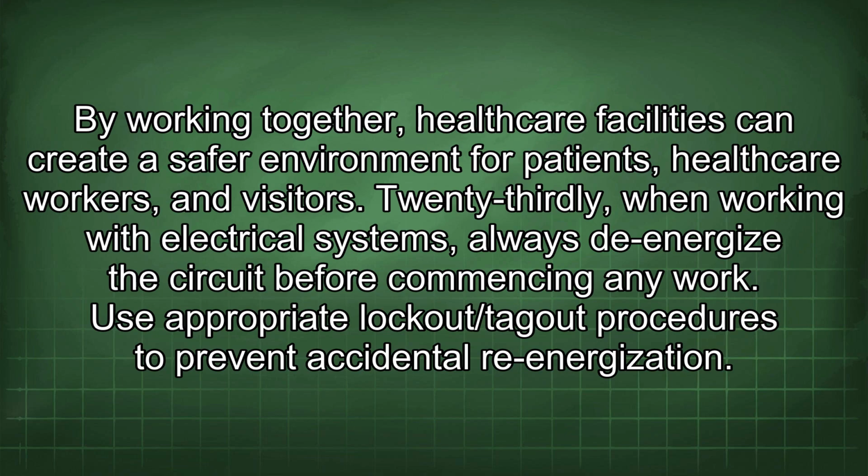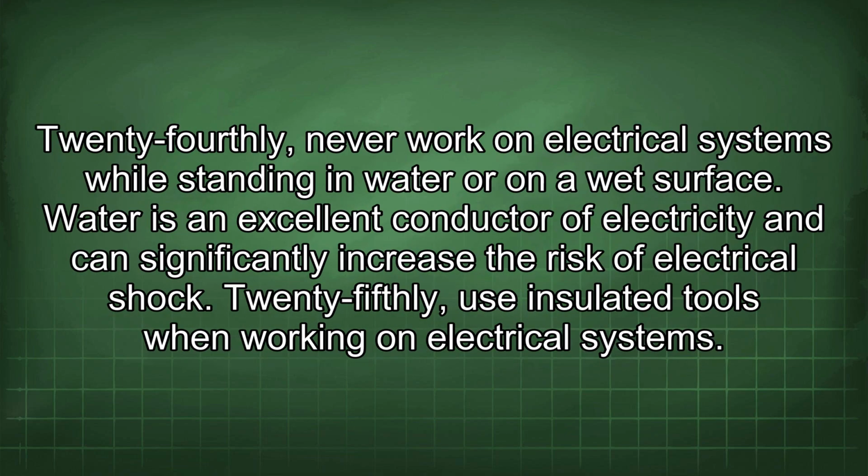23rdly, when working with electrical systems, always de-energize the circuit before commencing any work. Use appropriate lockout/tagout procedures to prevent accidental re-energization. 24thly, never work on electrical systems while standing in water or on a wet surface. Water is an excellent conductor of electricity and can significantly increase the risk of electrical shock.